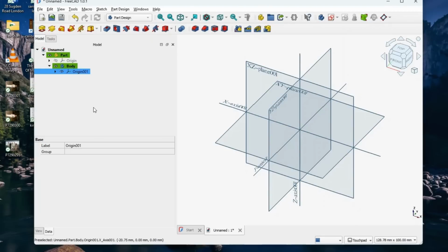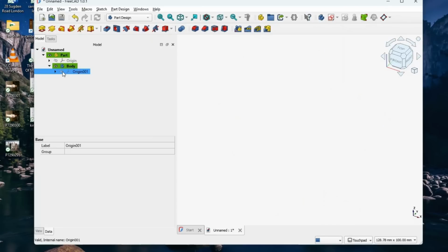I need to know that I'm doing it and which plane I'm working on when we're working on a particular body, because we can work on a body in the XY or the XZ. We can combine them into that part. But we're going to work on this particular body here on the XY plane and create some sketches. Let me just hide that again. There we go.